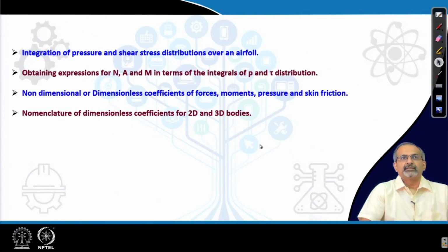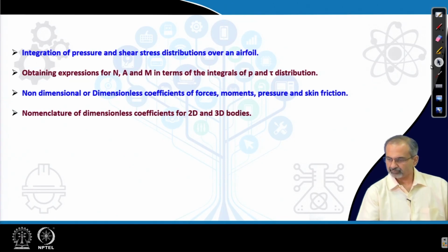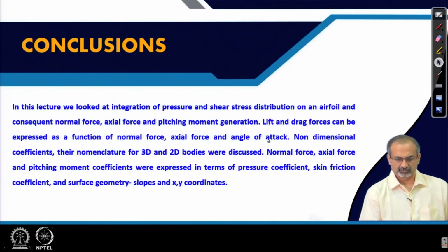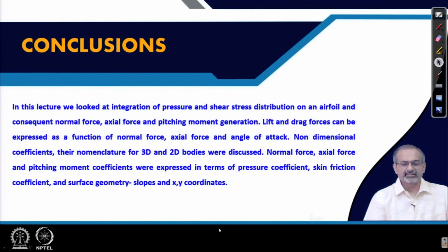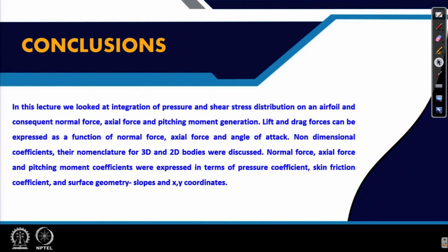So, we have discussed all these points which we planned to. We conclude this lecture by looking at the main points. In this lecture, we looked at integration of pressure and shear stress distribution on an airfoil and consequent normal force, axial force and pitching moment generation. We looked at lift and drag forces being expressed as a function of normal force, axial force and angle of attack,